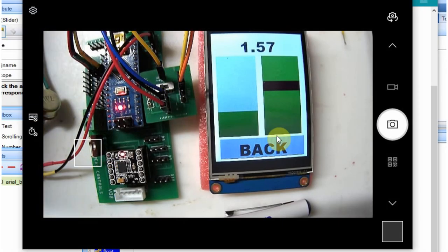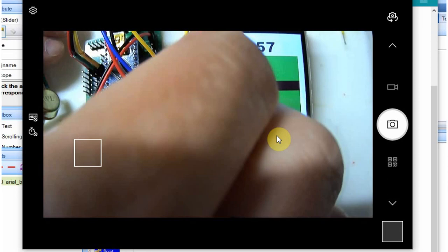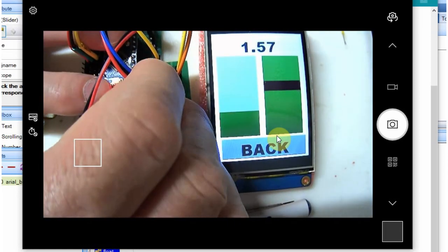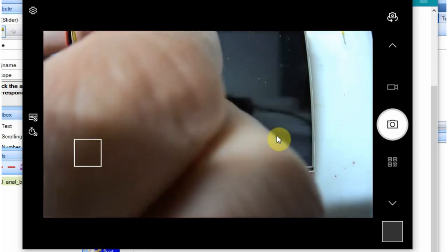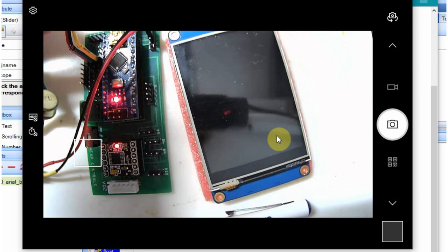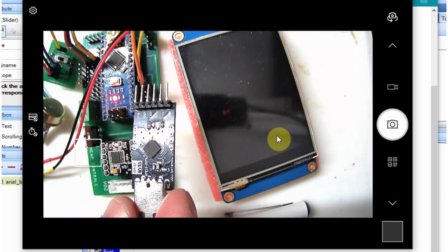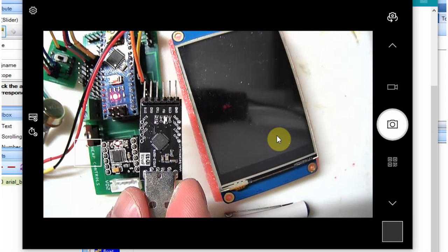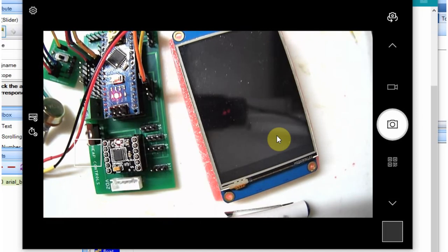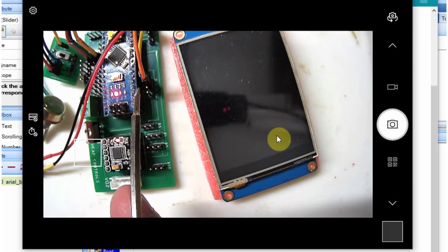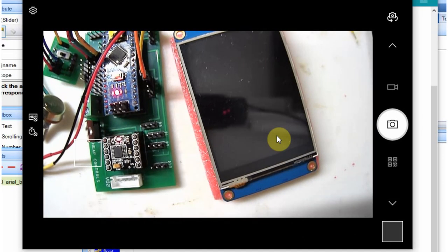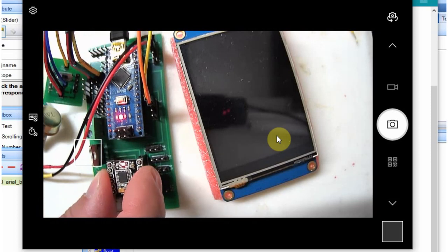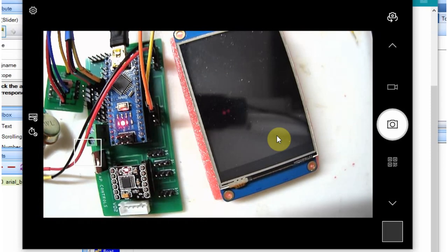And what I have is this little board here, and I can unplug it. And then I'm taking one of these USB devices and plugging it directly into the laptop, and I'm taking the output out of the Arduino on pins 2 and 3, the serial 2, and connecting it directly to the display.